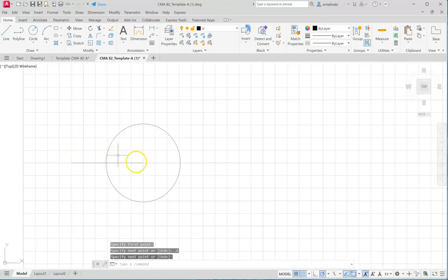And I have one line here going up. The copy that you have is not shown exactly equal, but I'm going to try to do this one equally symmetrical using this snap. And then one line goes up at an angle. This one I need to type. That's the best way to do it. You learned the coordinate system in the previous class by typing the at sign, relative, going some distance. I'm going to use just an approximation here.